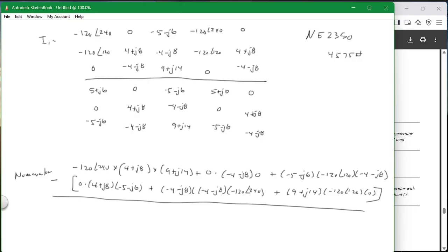But anyway, and then you need to mount your limit switches, and I don't tell you how to mount them. You just have to figure that out. We've got little nails that you can put in, and this is some I give you, but some of it you just have to kind of, okay, here's where this limit switch hits, and this is how this works, and all that kind of stuff, and you just kind of do it, and you get it. Once you get the limit switches in, and you figure out whether you're getting the normally closed or normally open, then that signal comes down, and then you have to say, well, I needed it the other way, so I have to put the limit switch in the other way.